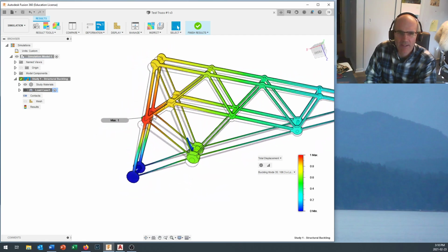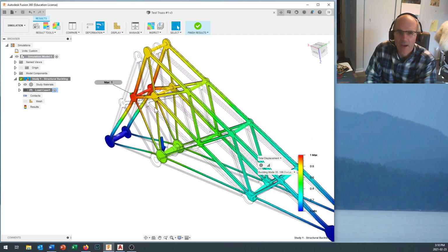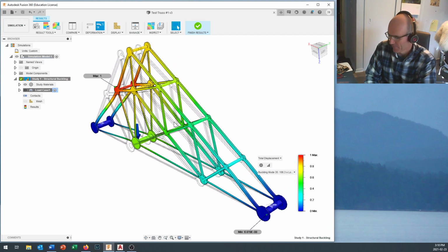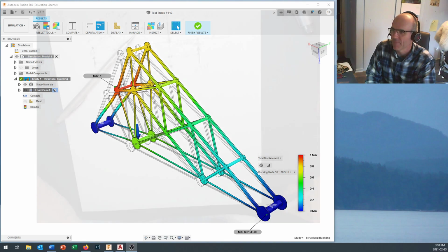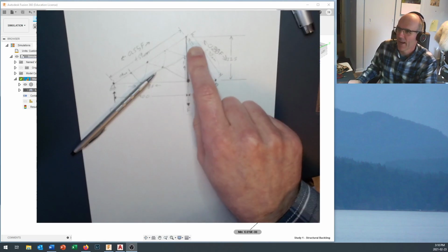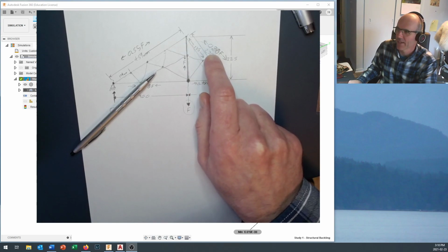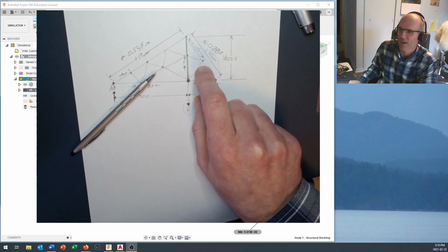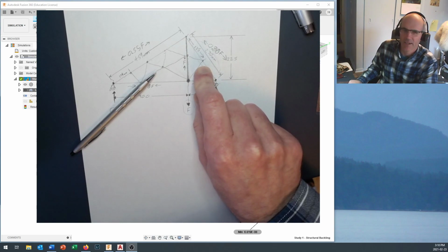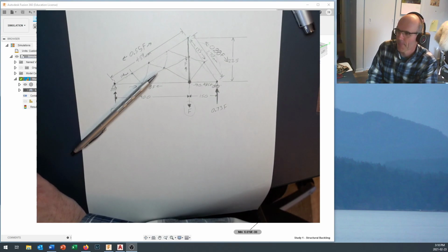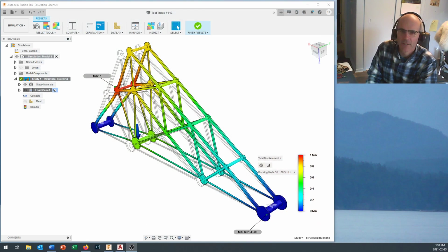We can tell that we're looking at a buckling failure in the back right here, which is nice because, as you'll recall, a little earlier we sat down and did some math on our sheet of paper, and we said, hey, look at this. We've got our longest members subject to our highest load back there. I'll bet that's where the buckling failure is going to be. We probably need to make those nodes a little bit stronger. So that's confirmed right on there.